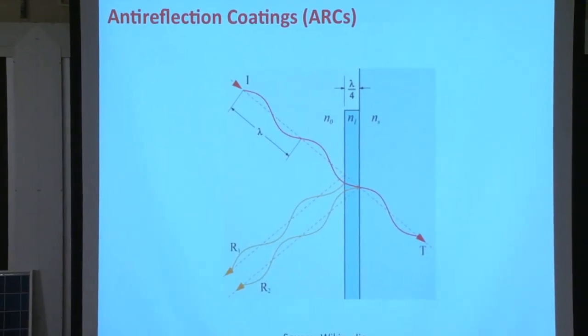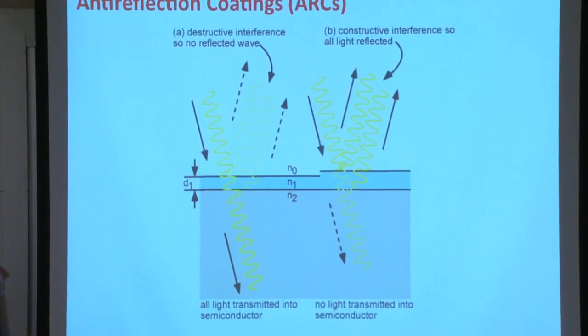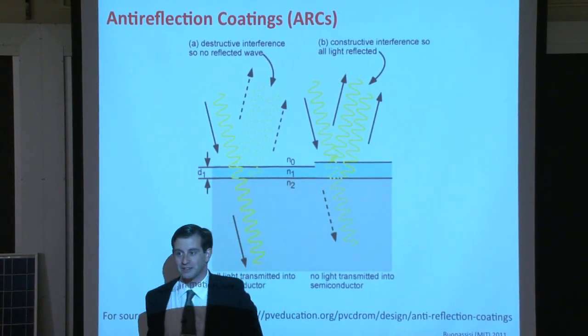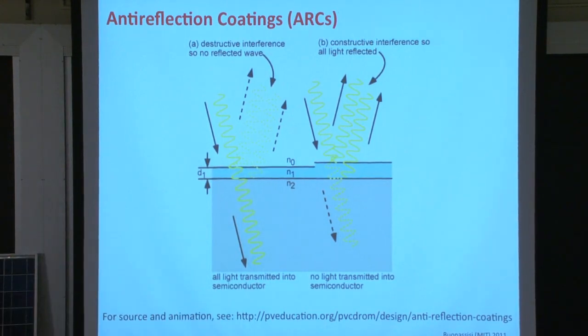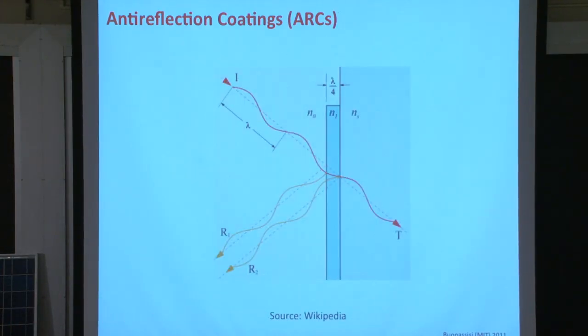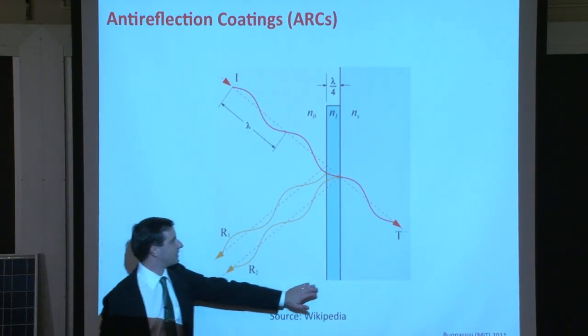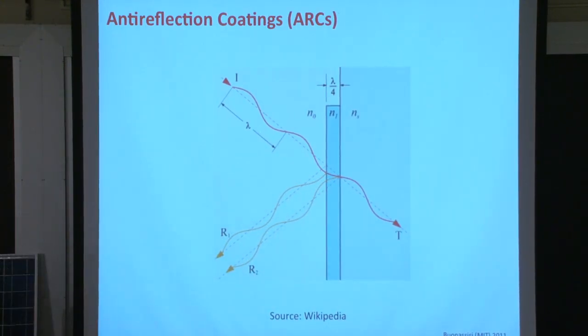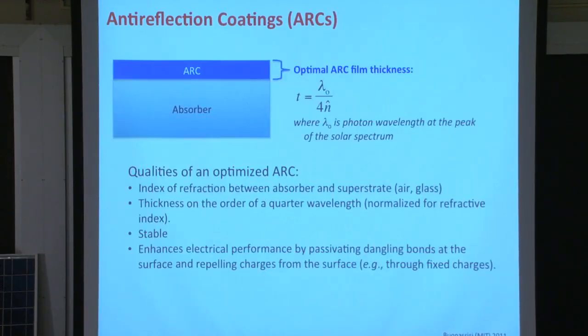And that's a really interesting property. You can begin varying the thickness of this layer and, of course, changing the nature of the reflected light. You can constructively interfere, if you like, and enhance the amount of reflected light as a result of this interference effect. Obviously, in most solar cells, we want to suppress reflection. And so we go to great lengths to make sure that this thickness, as well as the refractive index of the material, is optimized for a particular system.